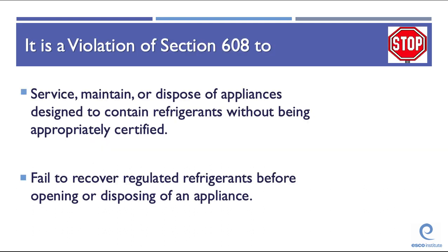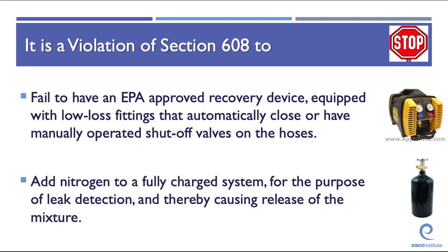It is a violation of 608 to service, maintain, or dispose of appliances designed to contain refrigerants without being appropriately certified, or to fail to recover regulated refrigerants before opening or disposing of an appliance. In other words, recover refrigerants and be certified to do so. It's a violation of Section 608 to fail to have an EPA-approved recovery device equipped with low-loss fittings that automatically close or have manually operated shutoff valves on the hoses.